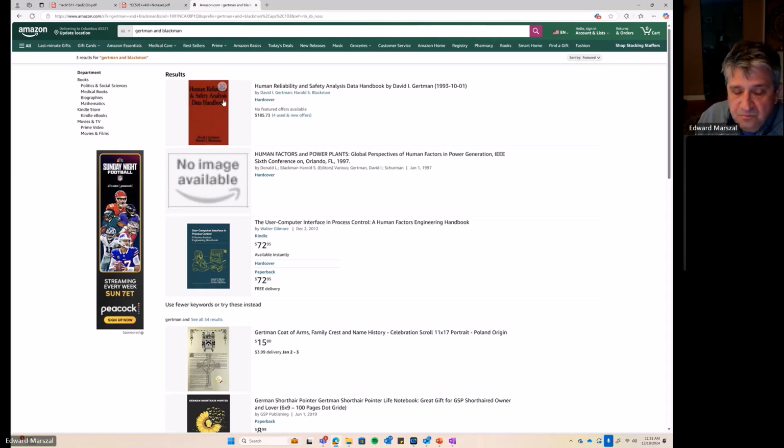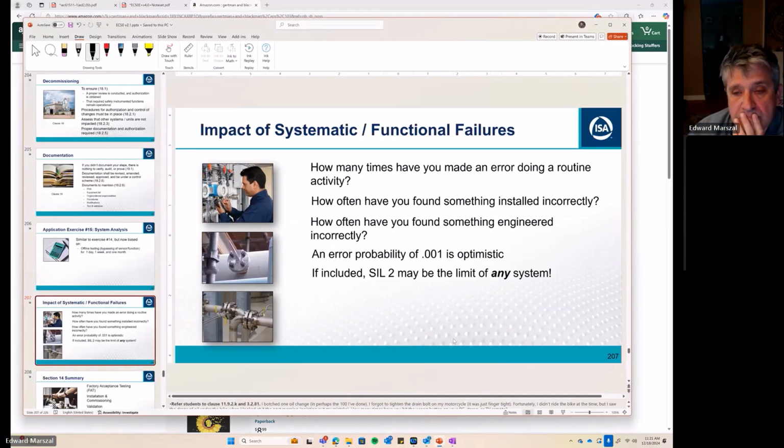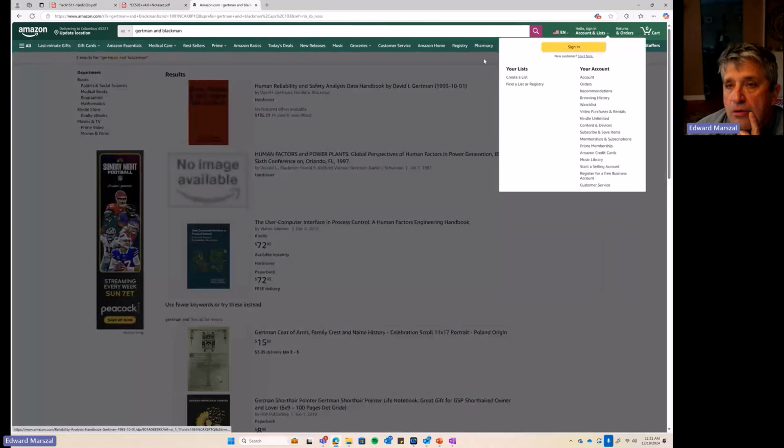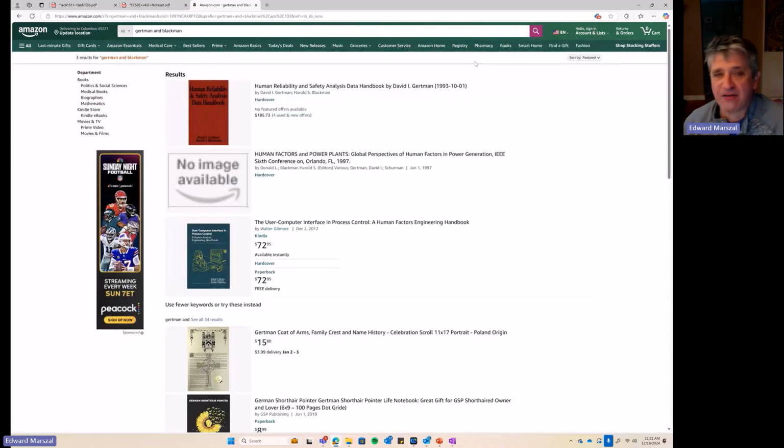Okay. As per definition, SIS could use any combination of sensors. Can we have a voted combination of a transmitter and a switch? For example, 2 out of 2 radar level transmitter and a tuning fork switch. Do the sensors have to be apples to apples comparable in terms of accuracy and speed of response? No. You're allowed to mix and match all you want.